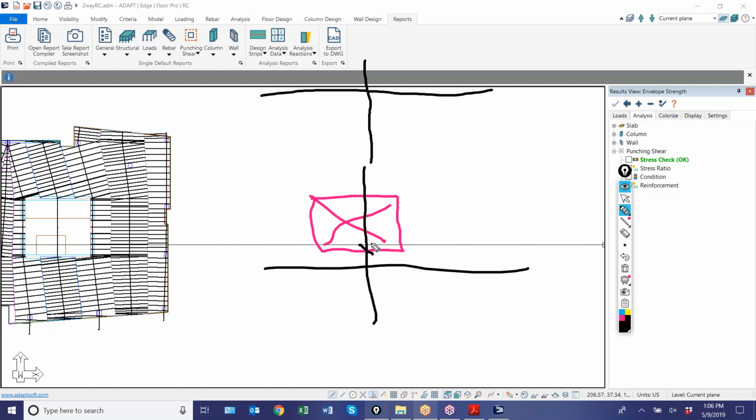This comes into the opening and exits out of the opening. So now in reality, when we look at this physically, we have slab, an opening, and then slab. This is like the section of the slab here and here. When the program designs for this, it combines it. It says add this to this, and you get some conglomeration of these two sections.